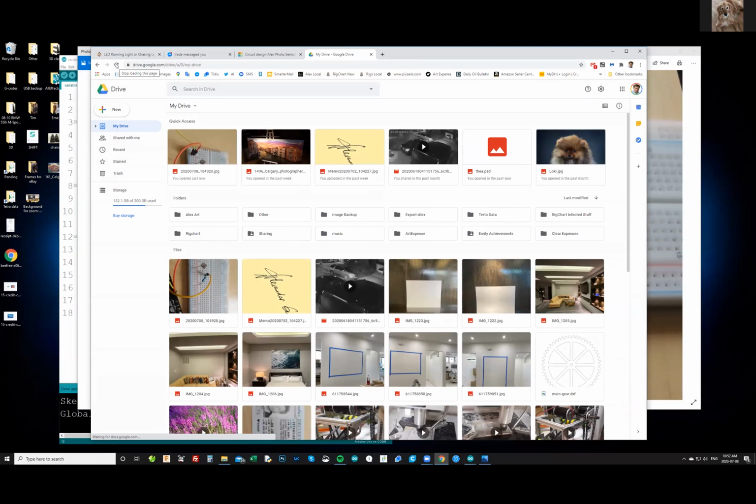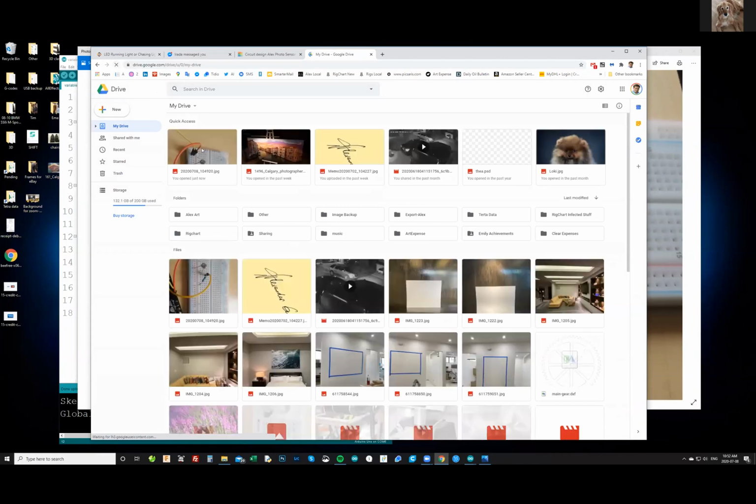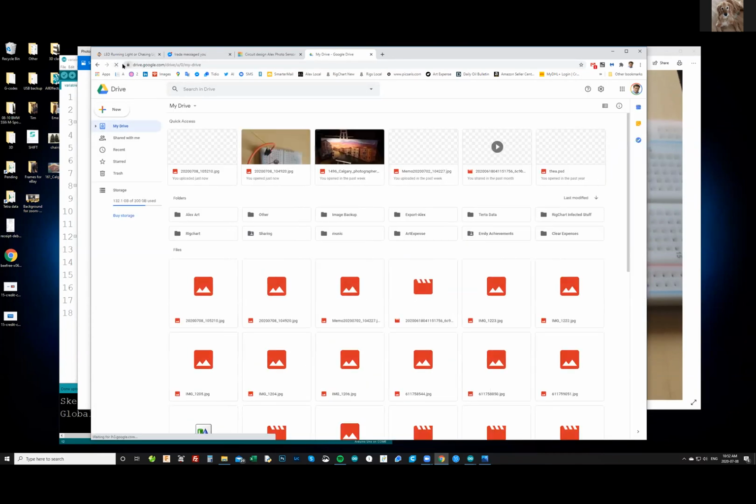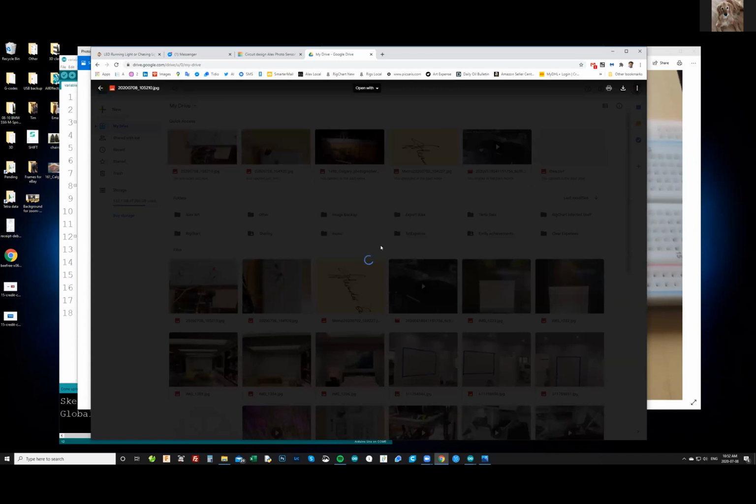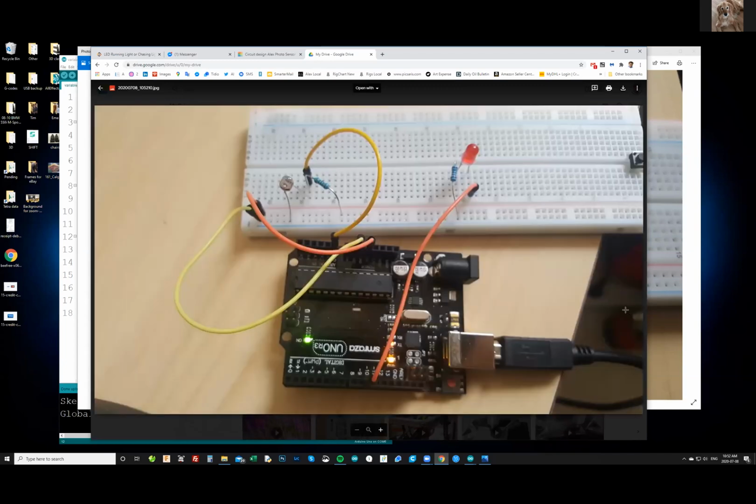Can you go back to the picture? Just a second, I'm getting another one. There it is. Is this better? Yep. You can see where the wires actually go to. So this is pin 10, the one that is controlling our LED. And now this is A0, going to the place where the photoresistor and 1K are holding hands. One end of the 1K goes to plus red, and another end of the photoresistor goes to negative. And these two just supply power to the entire circuit.